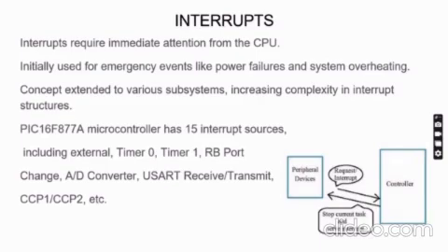We have implemented projects that demonstrate the use of interrupts and interrupt service routines, and we are using them in our main project, the micro project, also. The first thing it does is acknowledge the request, attend the request, and go back to the processing where it was interrupted. This is the block diagram for an interrupt service routine.